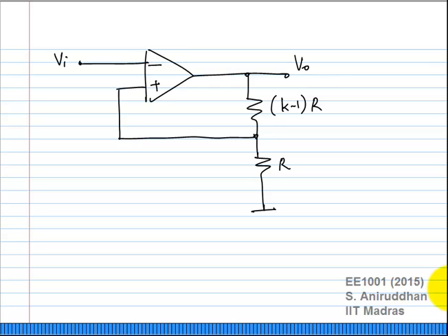But the equivalent circuit of the op amp as a voltage controlled voltage source is not applicable when placed in positive feedback. Okay, you can use it only when the op amp is placed in negative feedback. Do not use the VCVS model in the case of positive feedback.